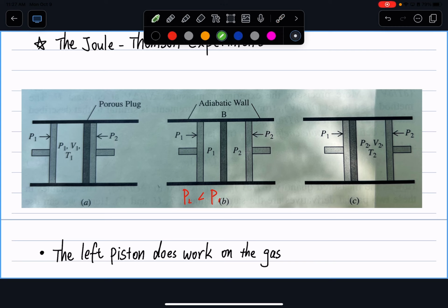So if you think about the whole process, the movement of your gas from the left chamber to the right chamber, the whole process is irreversible. But if you're looking at the work that's being done at each of the steps, because the gas can only slowly go through that internal partition, we have reversible throttling of the gas from the left part to the right part.